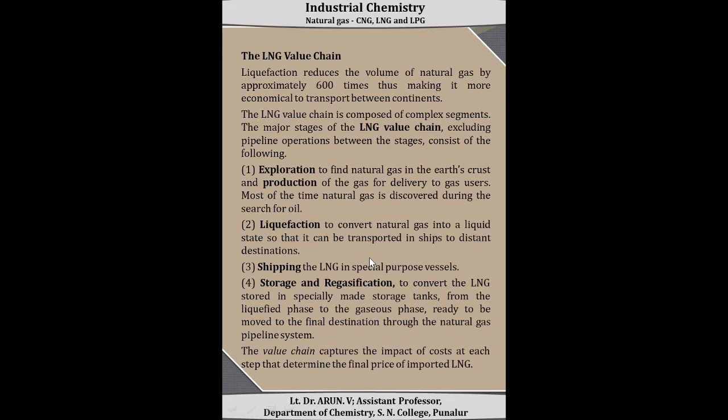Third step is the shipping. Shipping the LNG in special purpose vessels. And the fourth one is the storage and regasification. This step converts the LNG stored in specially made storage tanks from the liquefied phase to the gaseous phase, which is ready to be delivered to the final destination through the natural gas pipeline system.